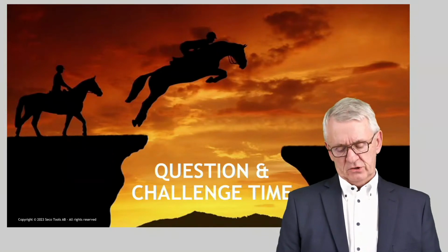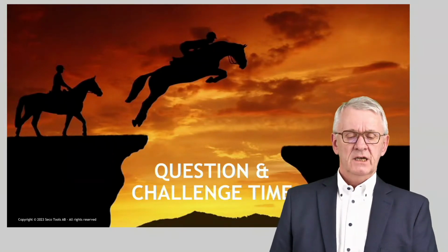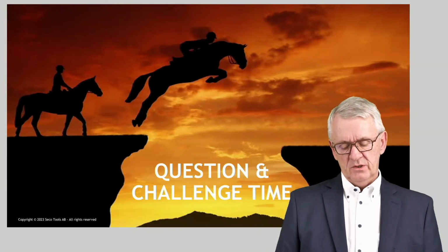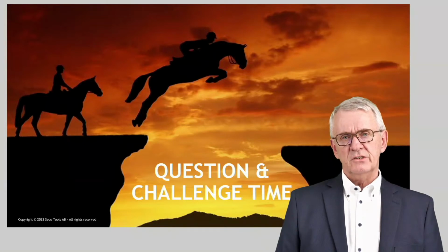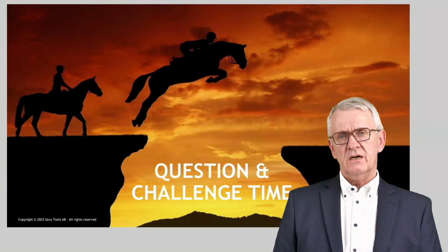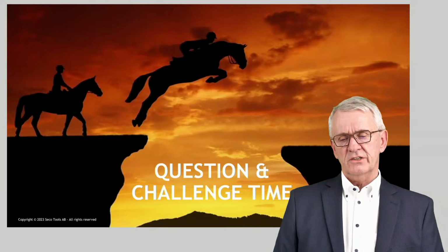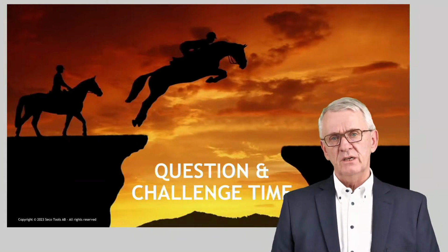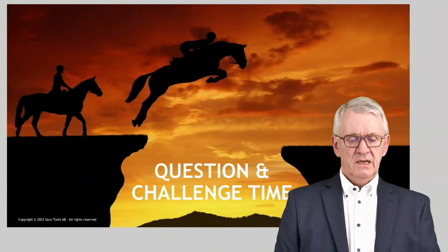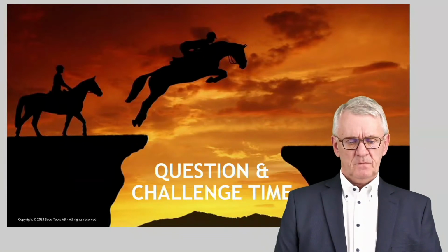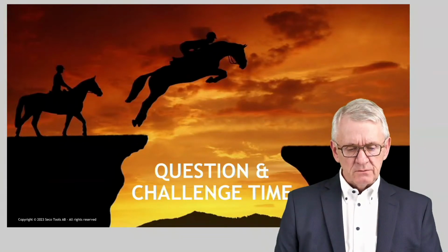Indirectly, yes, because to have a certain chip thickness, you have to modify the feed. But each time when I'm teaching, I try to make people aware that feed and depth of cut are only of secondary importance if we start thinking about how a cutting edge is behaving, and the conditions a cutting edge is demanding for it to cut well: the power, the stability, all that type of things.